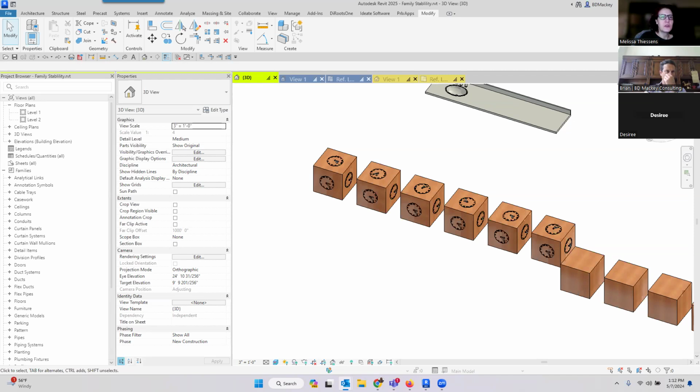Okay, so along the printing lines, Rick's saying, I like using print sheets in PyRevit using the Bluebeam driver. Your thoughts? Do you like DiRoots, the new built-in PDF exporter, or something else? Pros, cons? The one thing I love about PyRevit, which I haven't updated the new one for 25 yet, is the fact that you can print based off of a schedule. I can go to my drawing index and say print it in this order, and it prints in that order, or it just grabs those sheets.